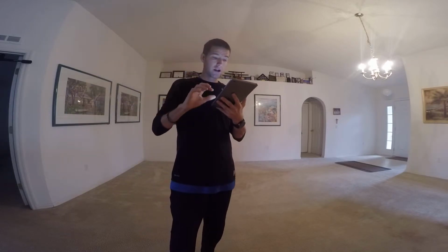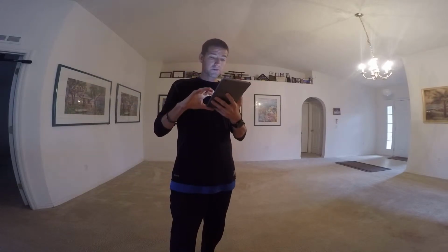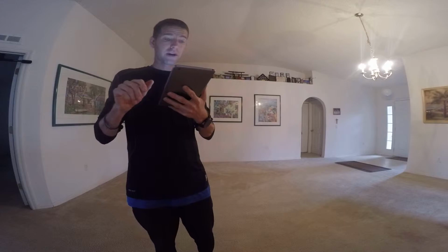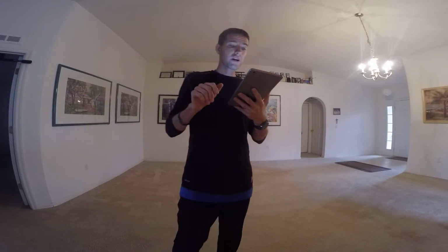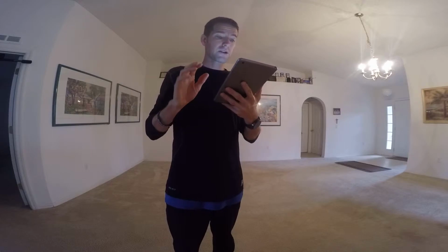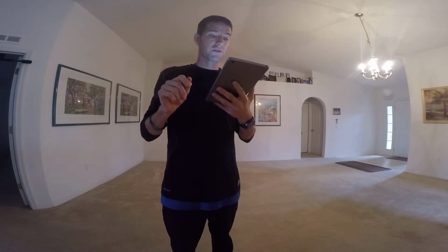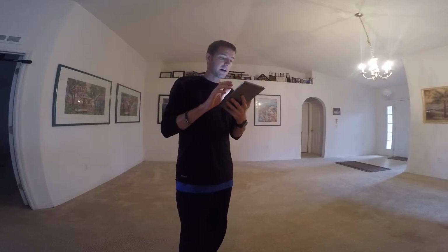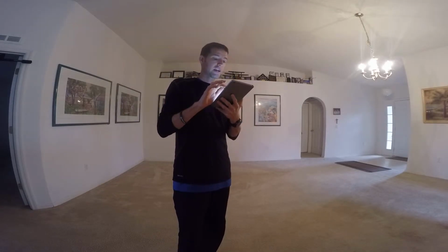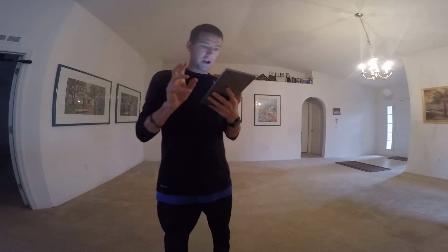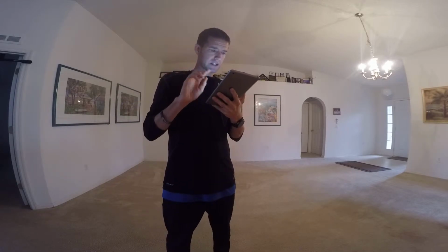Airflow in forward flight. Airflow across the rotor system in forward flight varies from airflow at a hover. In forward flight, airflow is opposite the aircraft's flight path. The velocity of this airflow equals the helicopter's forward speed. Because the rotor blades turn in a circular pattern, the velocity of airflow across a blade depends on the position of the blade in the plane of rotation at a given instant, its rotational velocity, and the airspeed of the helicopter. Therefore, the airflow meeting each blade varies continuously